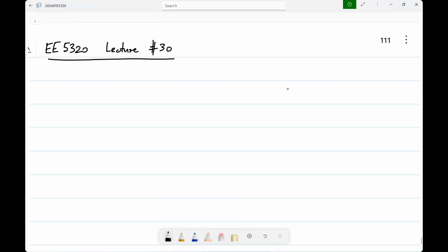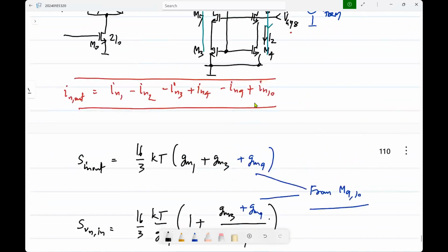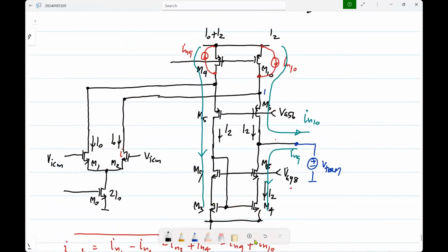We have looked at the folded cascode opamp. What it offers is a higher output signal swing because of two things. One is, there are two transistors to the top and the bottom. And also, earlier, in either the simple differential pair or the telescopic cascode opamp, the output was connected to the input transistor in some way.